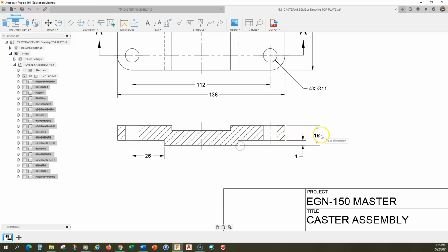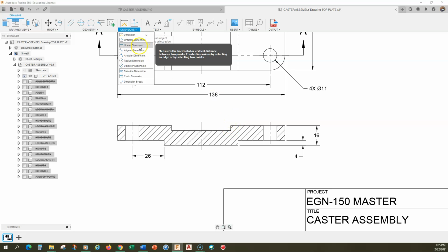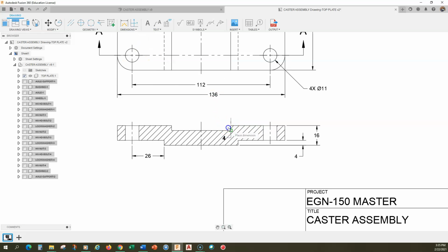You have to also think from the point of view of manufacturing. We're going to start with a sheet of whatever this is, steel. And we're going to cut this away and cut this away. So having that dimension in there and having the overall dimension is going to help us get started. All right. And finally, we can't forget this, right? So we do have to say how far this is going to cut in, right? So we put it in there, and please don't leave it like that, right? We're going to pull that out like that.